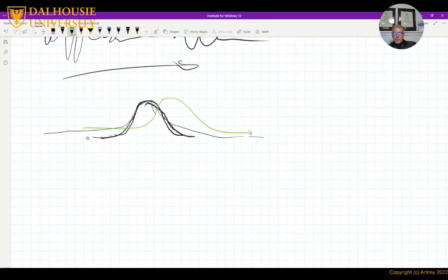The black one is one channel and the green one is another. If I put them like this next to each other, then this part will overlap, which means that one channel will overlap another. Overlapping means that some of the signal will scramble and we won't be able to retrieve it correctly on the other side. So we have to separate them. But by how much?